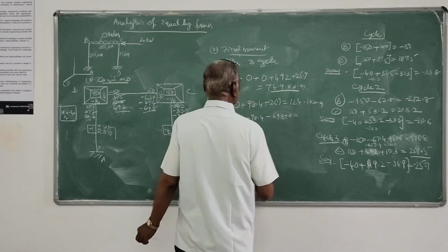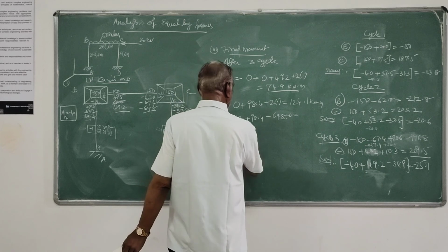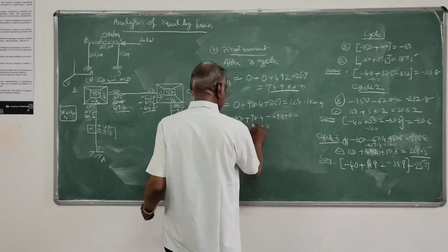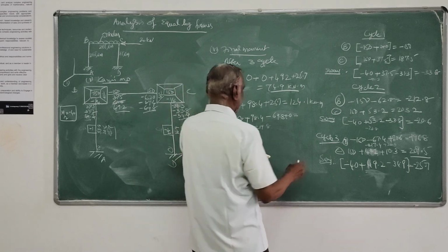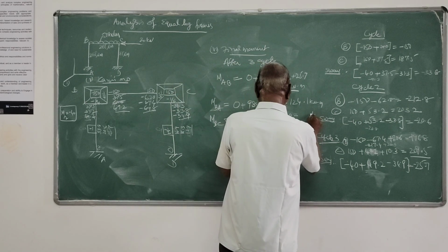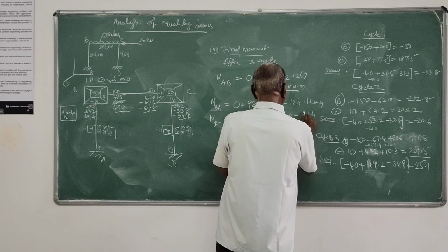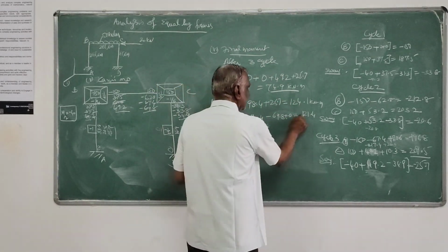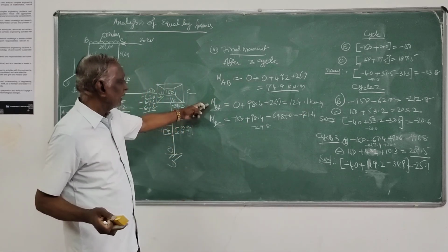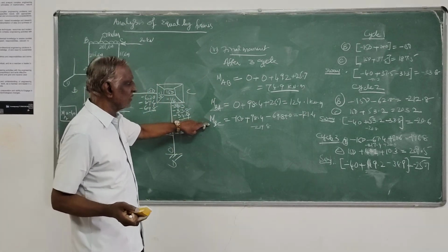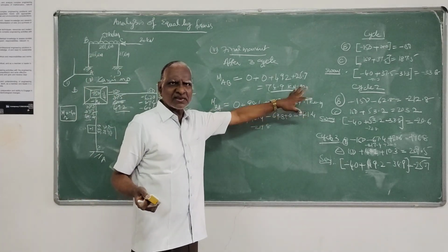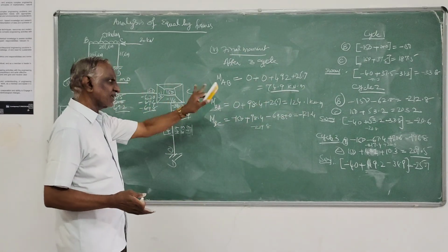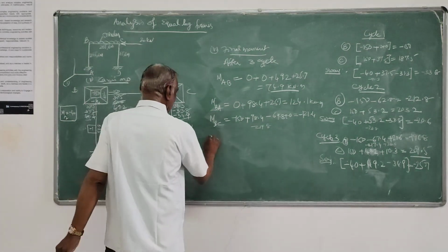So this sum is equal to minus 121.4. The check is MBA plus MBC has to be 0. I am getting this error because I am closing at a lower cycle, so that is acceptable. I will leave it.